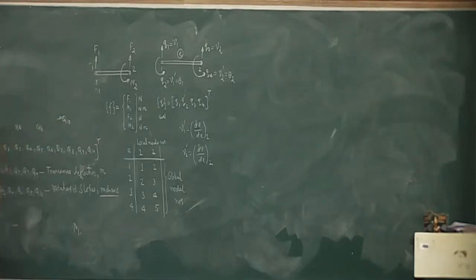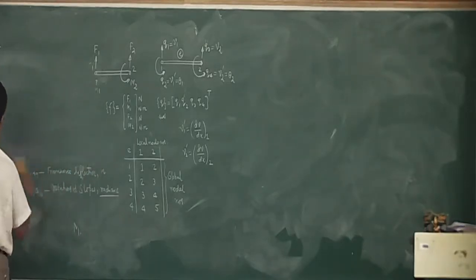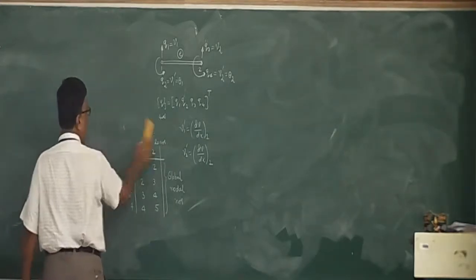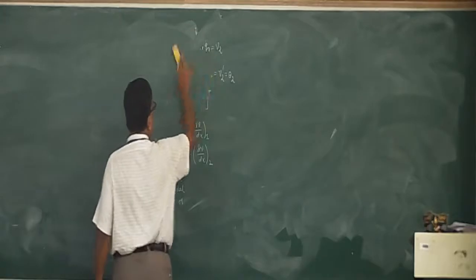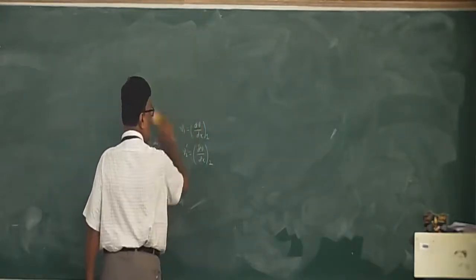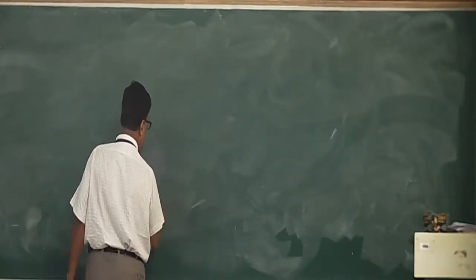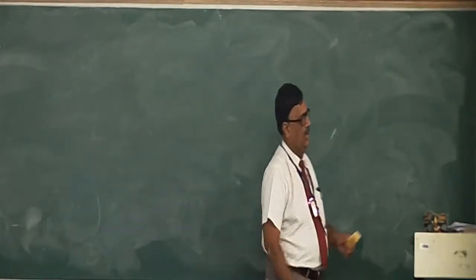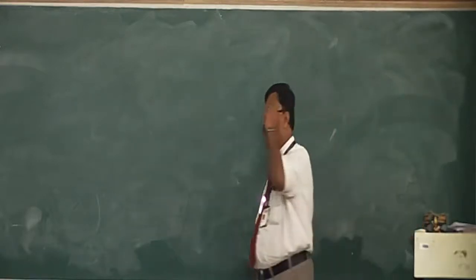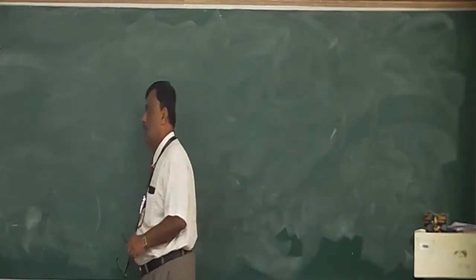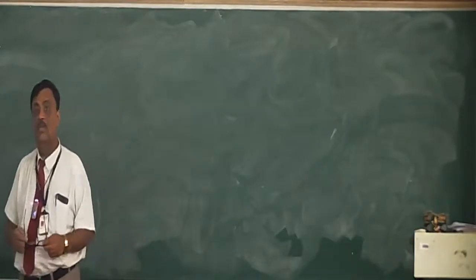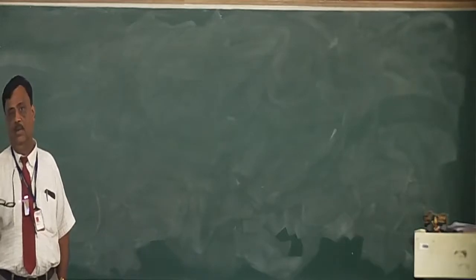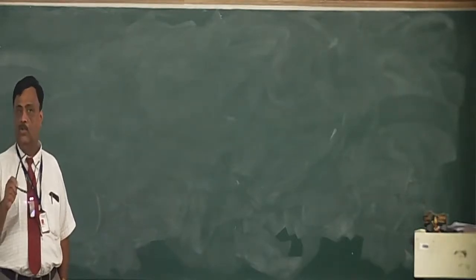Now, another very interesting point I would like to tell you here is about the interpolation. In the previous classes we have seen one-dimensional elements with 2 nodes and 3 nodes, and we have also considered 2-dimensional truss elements. There we defined the shape functions, which were linear or quadratic in nature, and that's why they are all called Lagrangian shape functions.